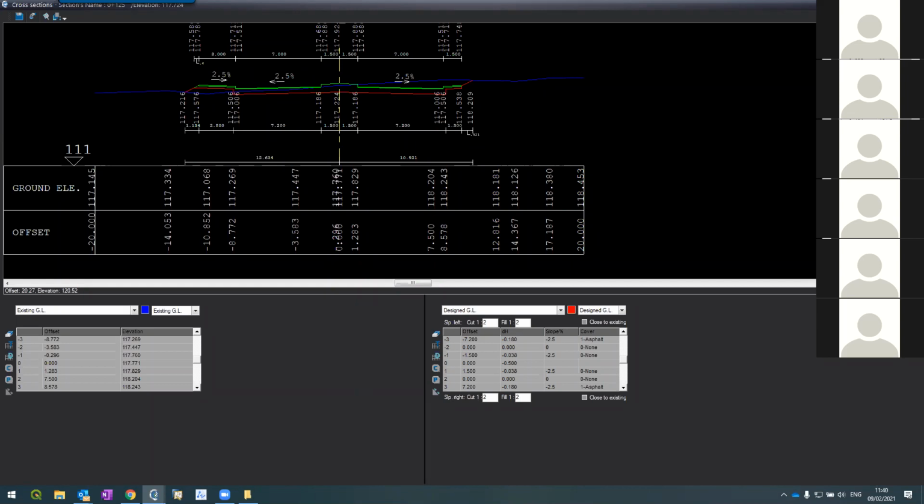In fact, as I said, I can combine the two together. You see that what happened in road number 2 is that I used extract. It means I predefined the geometry, then I create templates and apply it on the geometry. On road 1, I did the opposite. I used the cross section to create the geometry. Which method is better? There's no such thing. You decide, depends on the situation. Usually, if you have a lengthy road with not much change, maybe it's better to run. Actually, you can start with one, change the geometry and extract back.